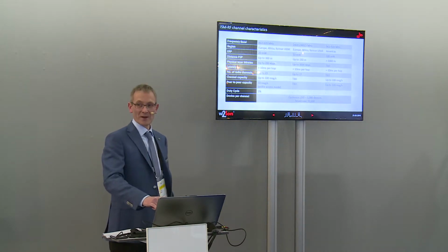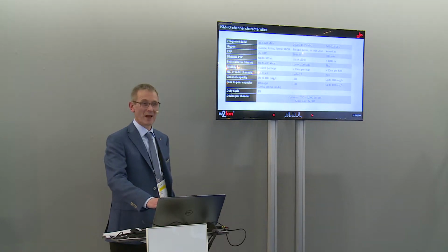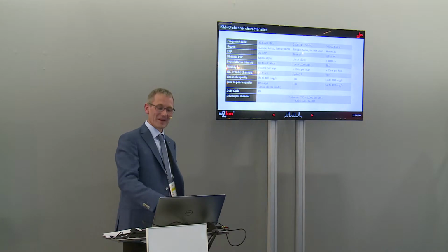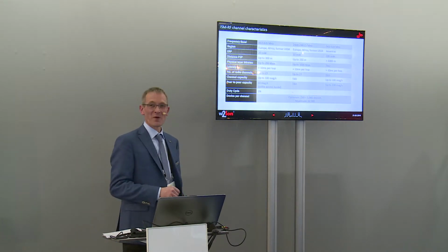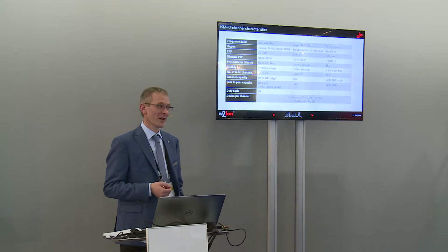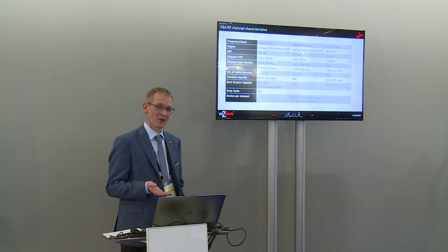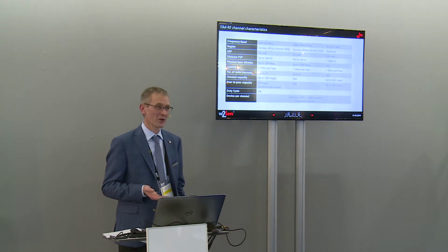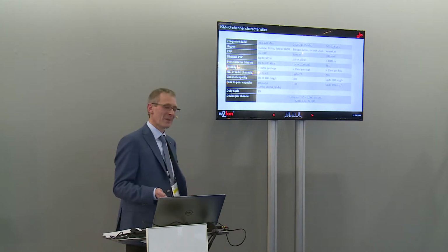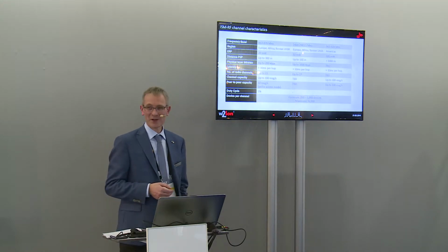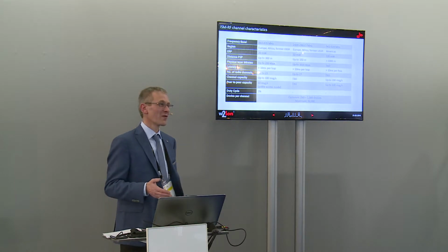There are different regulations in the Americas. I don't think that we have that restriction with the polite access mode in the US or in the Americas. Same thing with the 2.4 gigahertz frequency. There's no polite access mode on the 2.4 gigahertz channel. The sad thing about the 2.4 gigahertz is we do have less transmission power, and of course a shorter range.